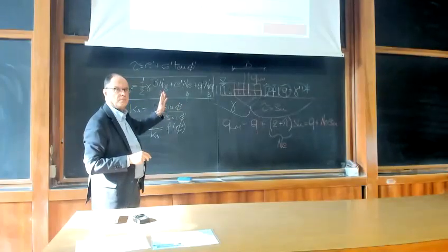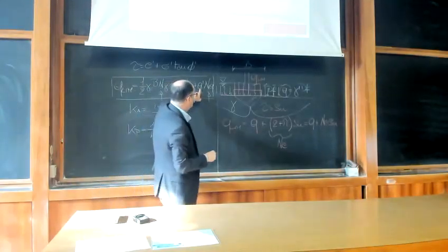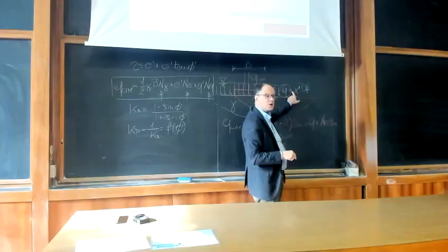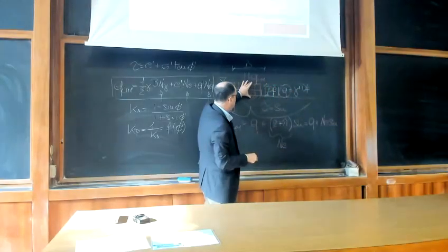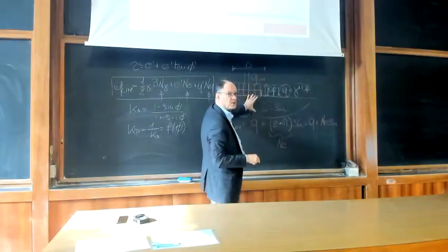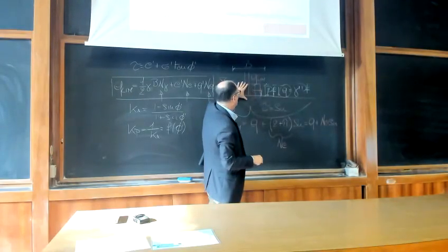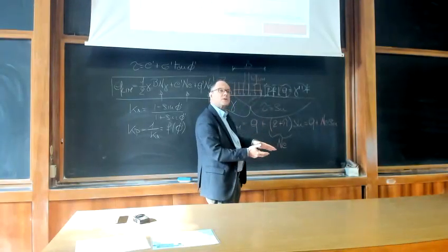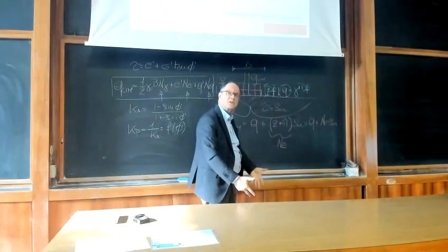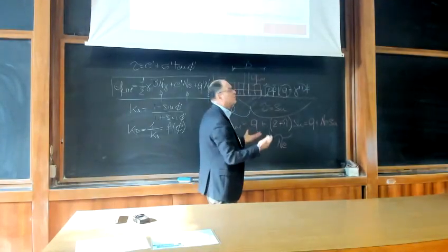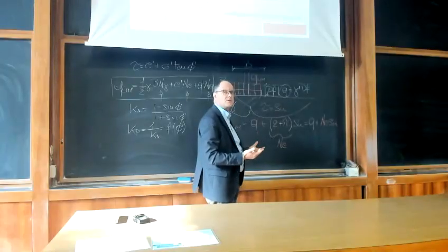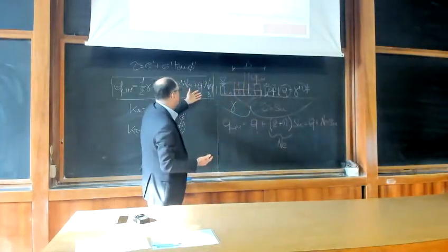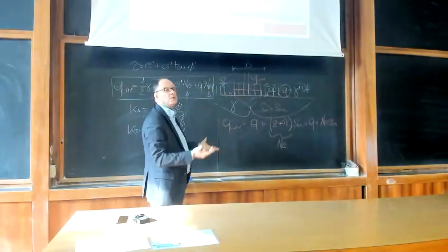parameters which matter. For example, the overburden stress, we had already noticed here, is important. So once again, the deeper your foundation, the better it is. Now, of course, if you want to build a shallow foundation under 4 meters instead of 1 meter, it's more complicated. You have to excavate 4 meters. It's all more complicated and more expensive. So this is an important contribution to the bearing capacity. But you have to consider if you really need it.